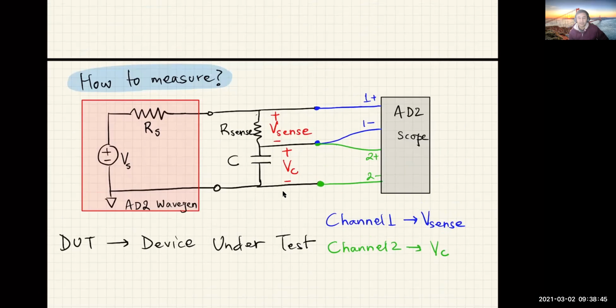As opposed to using an 82, where you have to measure the voltage and then extract the current through a sense resistor. On LT-SPICE, you can directly measure the current, but I don't want you to do that. I want you to get a sense of how to do the same measurements and exercise of measuring the voltage and calculating the current from it